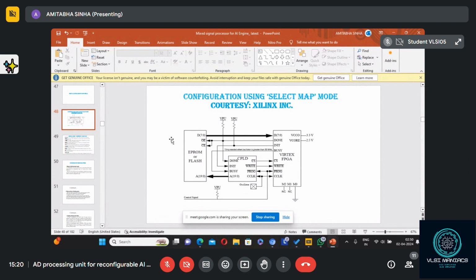So depending on the command from the CPU, this CPLD will organize it such that the bit stream will be transferred one by one in byte form from the serial PROM to the FPGA. And once the entire bit stream is over, then the CPLD will send a control signal, which is not shown here, to the CPU.